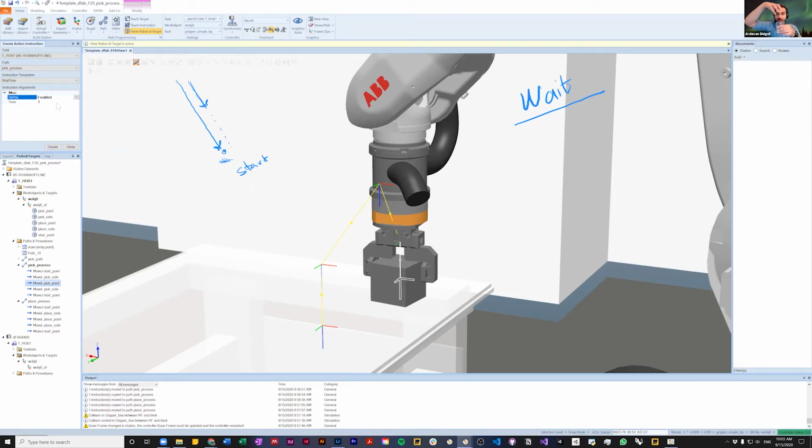And if you don't enable this in position, it means that the robot is going to start closing its fingers before getting to the glass. But if you have that in position on, it means that the robot gets exactly to the glass, then tries to close its fingers. So to be on the safe side, let's keep these two commands here.